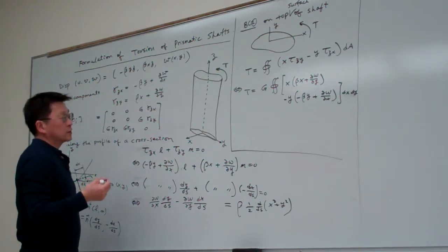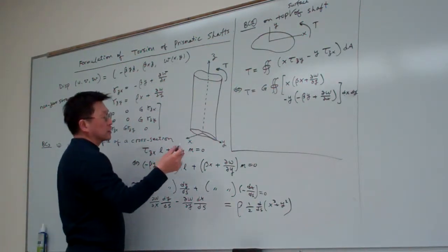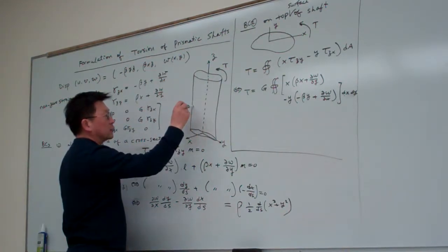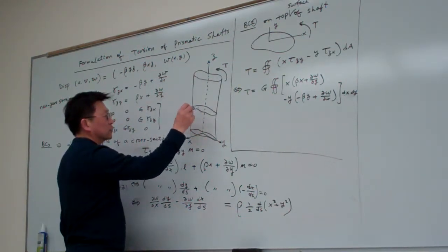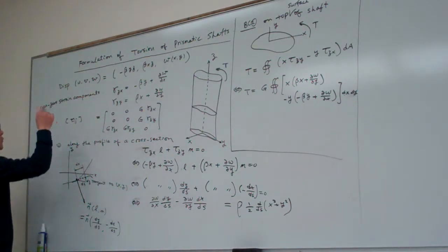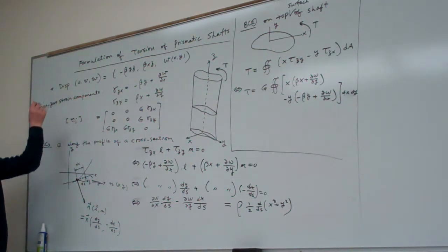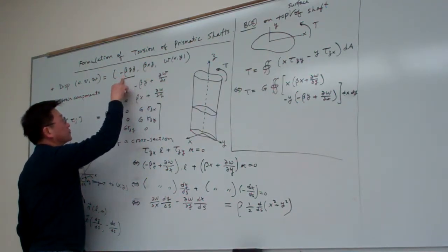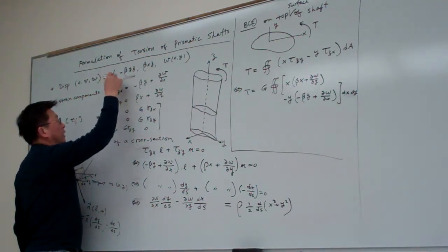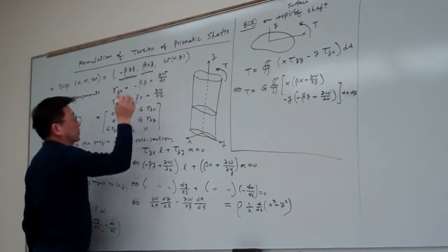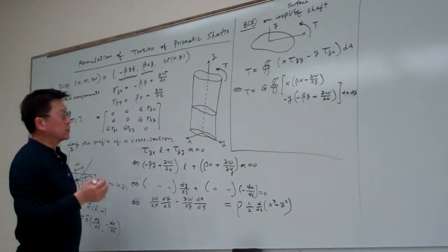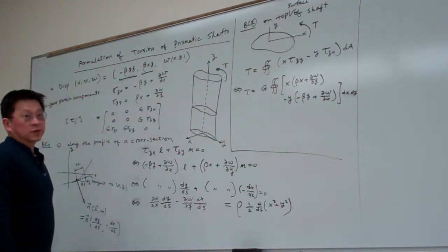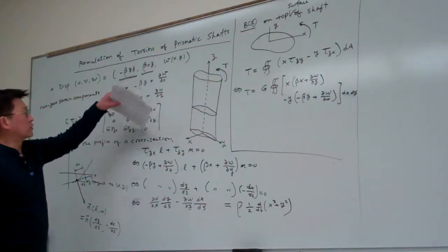Again, we have three assumptions. The first one is that any point in any cross section undergoes rigid body rotation, and that leads to the formulation of the displacement vector, in particular the two components here. The x component and y component are based upon this assumption, that the points on the cross section undergo rigid body rotation. So from there we can derive this.